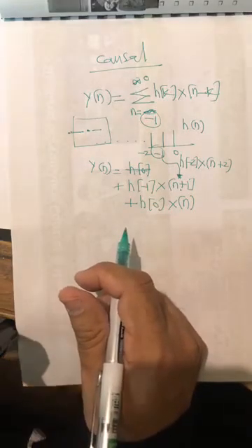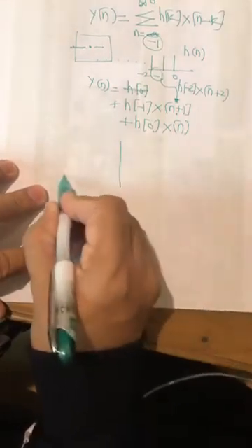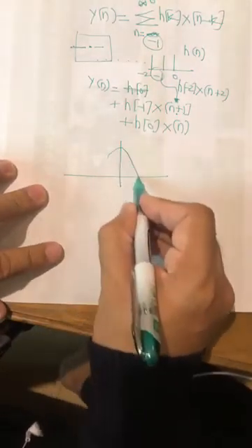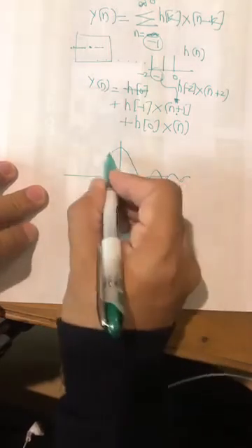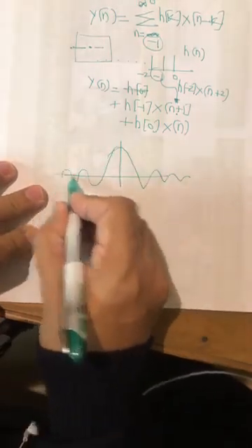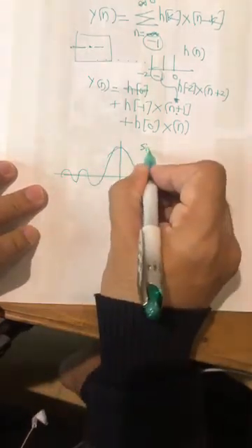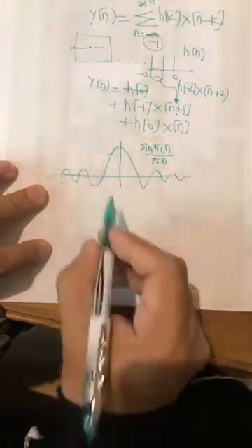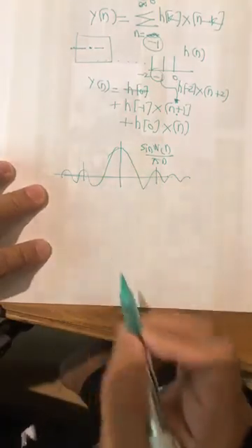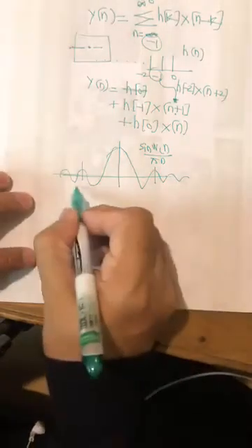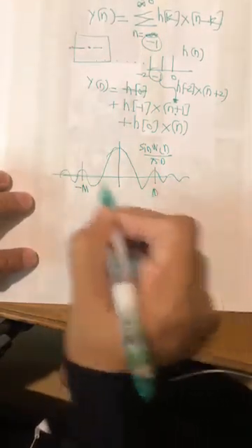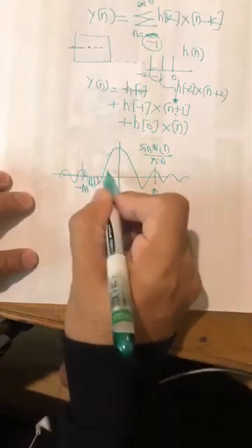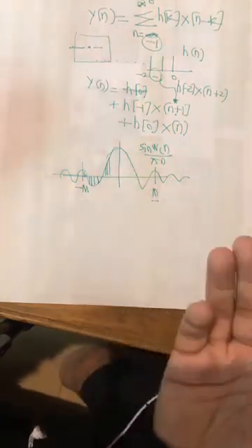But in 1D signal processing, when we are designing a system, remember that the ideal system in the time domain has an infinite impulse response, an infinite sinc. To make it a realizable system, you chop it out and throw away the rest of the samples. You keep the samples from -m to m. What m is depends on how much you are willing to spend.